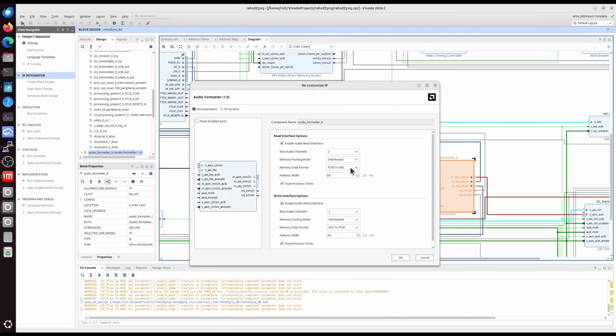And so when I came into this, I had it set to PCM on both of these, because one article said to do that, a different article said you need to stick with AES to AES. But in the end, it was this configuration you see here that finally got audio working fully for me. I had also experimented with an updated codec driver for this specific codec hardware, the WM8960. I tried that, it didn't make a difference as I was troubleshooting all of this.